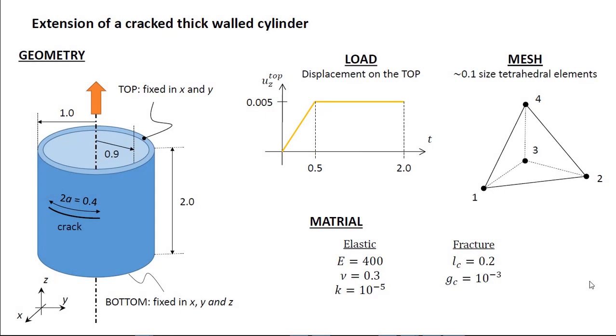To sum up what we did, we created a cylinder with a cracked side. We extended it in the y direction. We saw a beautiful symmetric crack opening. We increased the displacement on the top until a certain time, then left the top there. However, we saw that the crack propagated in an unstable way. Thus, the static method actually calculated the crack opening without actual loading. For this model, we used the new tetrahedral element, and that's it.